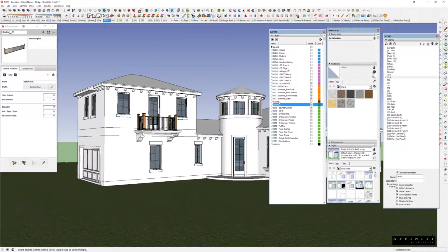I'm going to actually delete this. And just a quick thing to show since I'm doing it, I'm going to delete these options. To delete railing, I don't want this railing 2 anymore. So I'm highlighting the layer, and I'm going to delete it. And I want to say delete contents because I don't want that option anymore.